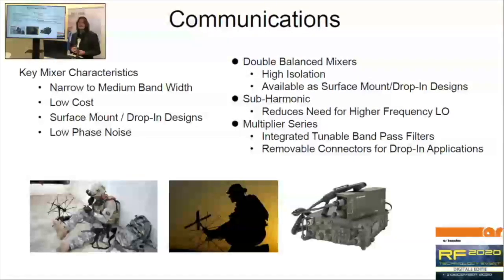And in some cases where you have multiple tuned passband filters, there is the multiplier series, where you could use a multiplier or a comb generator and just filter or switch between the different LOs quite quickly. And that means you can tune quite neatly to a certain channel.